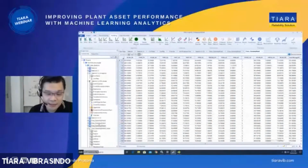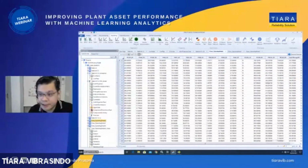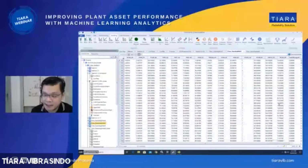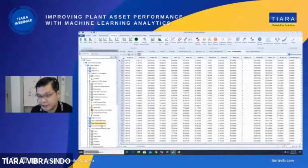Now, if I look at something very interesting, if I look at operating mode 3, take note of the energy consumption. It's about 500 to 600, mostly 500 to 600. If you look at operating mode 2 of the compressor, it is about 400 to 300, the values, right? If you look at operating mode 1, it is almost 0. So when you look at this data, you start to see something very interesting. It picks out the patterns. And once you look at the patterns, you can tell this is when the compressor is almost not running. So it is a different operating condition of this compressor, okay?